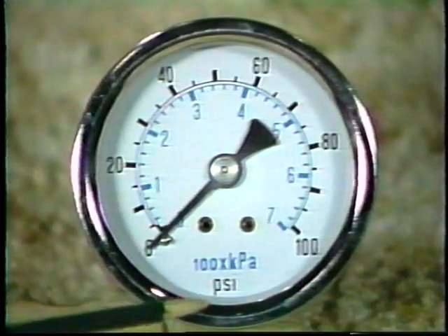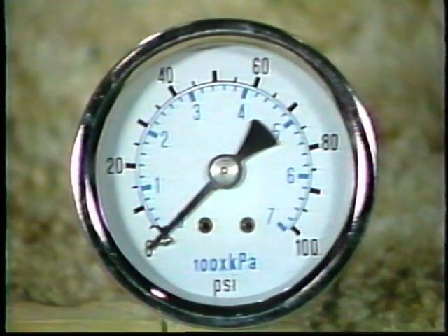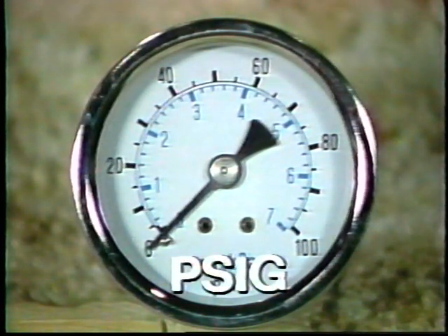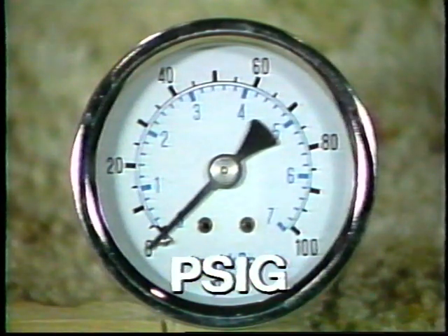If only the notation PSI is used in identifying a pressure, such as 10 PSI, this is assumed to be PSI-G, or gauge pressure. A common pressure gauge, when not connected to anything, will read 0. This is a 0 gauge pressure.